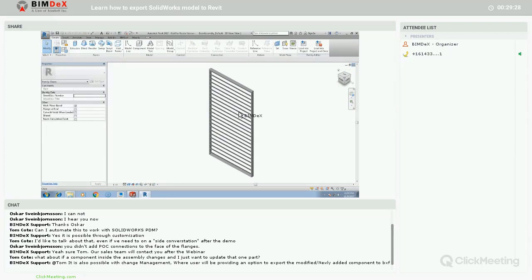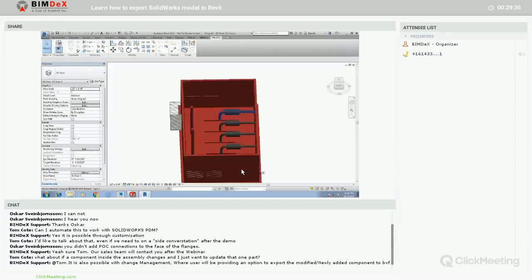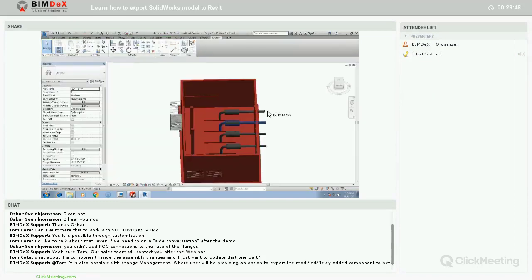This is an instance. So what I'm going to do is edit this geometry property. And you see all the instances of its geometry have been affected.